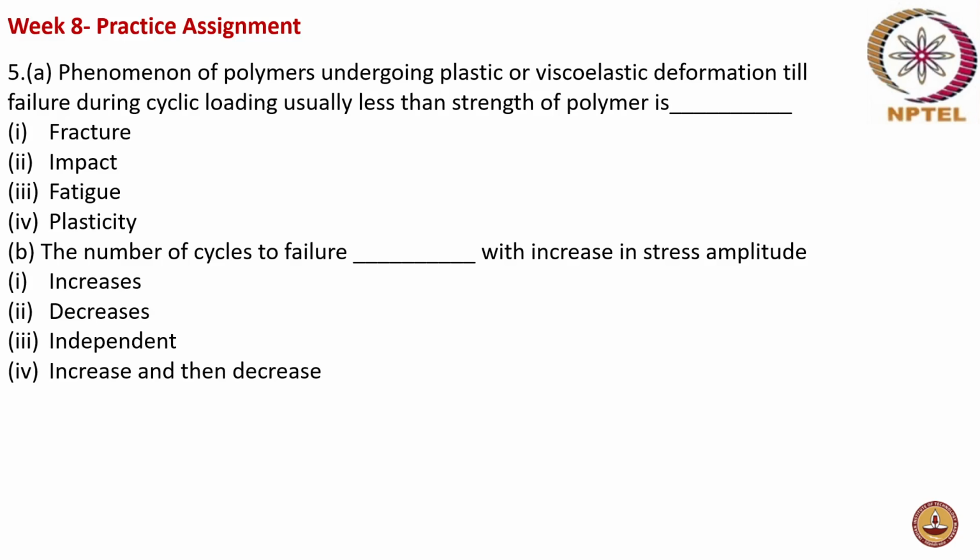So, polymer is undergoing some cyclic loading. So, during the loading and unloading, there will be some elastic and plastic deformation. But eventually, the material is failing. So, this cyclic loading, that is, it is loaded and unloaded, loaded and unloaded, until failure. This phenomenon is actually called fatigue.